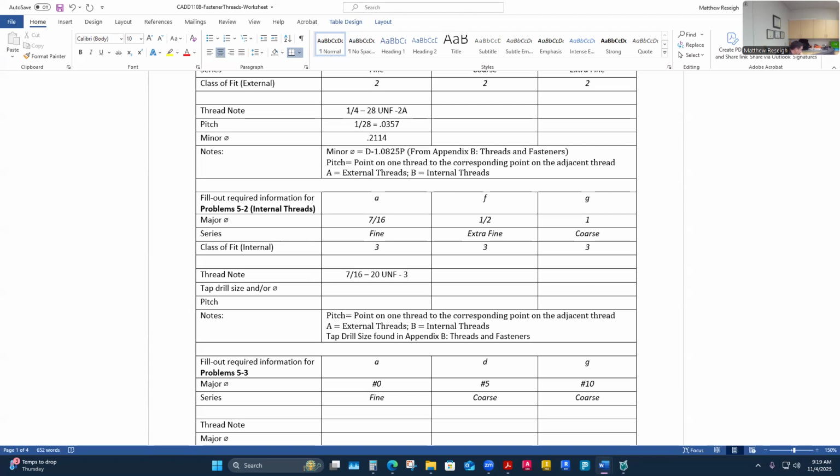They're saying the 3 is for the close tolerance. So they've actually used a fastener here that I'm not used to using too much. 2 was way more common as a general purpose tolerance. So 3 is that fine tolerance. B is the internal, so this is a 3B. A is external threads, B is internal threads. Yes, okay. So this is the correct thread note. Yes, I like this.